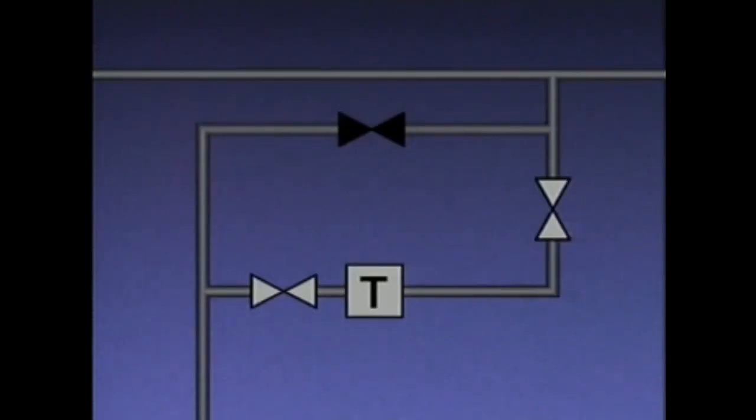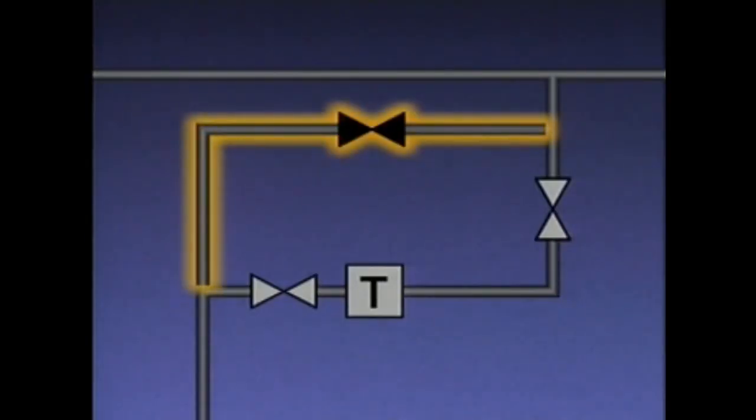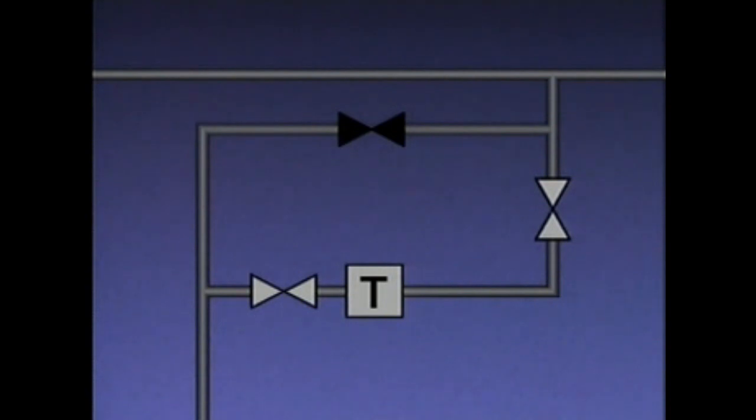Steam trap piping usually includes a bypass around the trap. In order to take the trap out of service, the bypass valve is opened until flow is detected. This allows any condensate in the steam line to drain. There will be some steam loss while this is done.